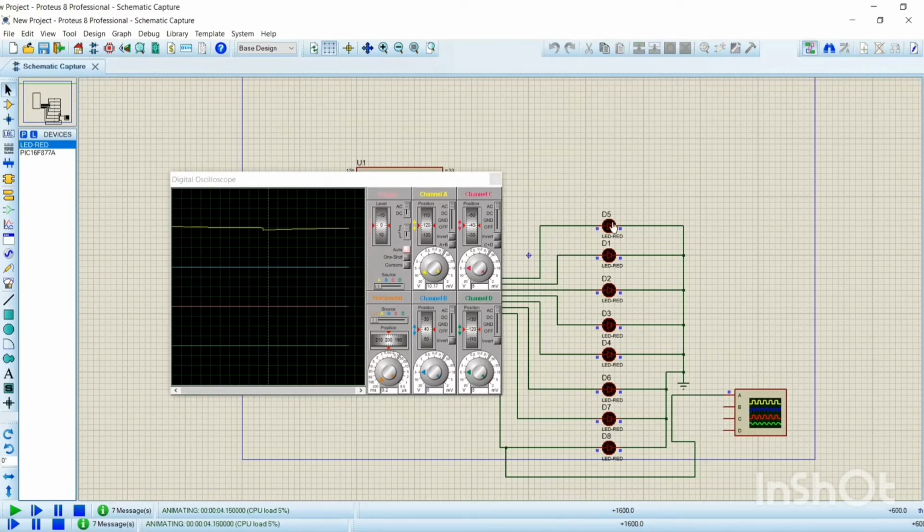As you can see in here, there is a delay in the blinking LEDs. Let's check whether our delay is correct or wrong. I have used this here, and 1 square represents 200 milliseconds. We need to check whether our present delay is correct or wrong.